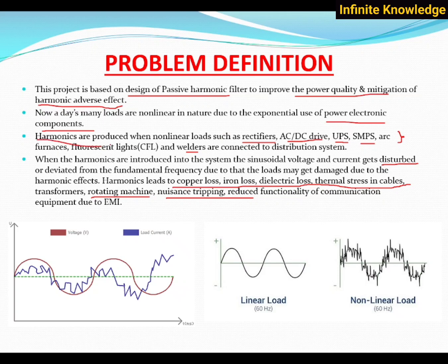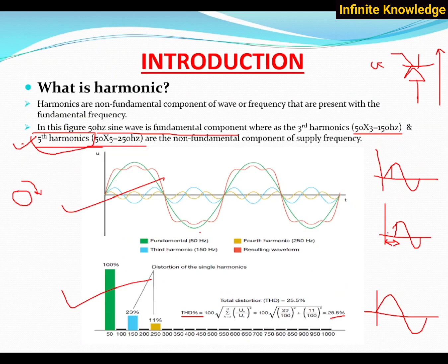And in industry, you might notice that your LED light filter is damaged, or even if you connect proper LED light drivers, they fail after 2 to 3 months, even though the lifespan is more than that. It all happens due to these harmonics and the different spikes that are continuously in our system.